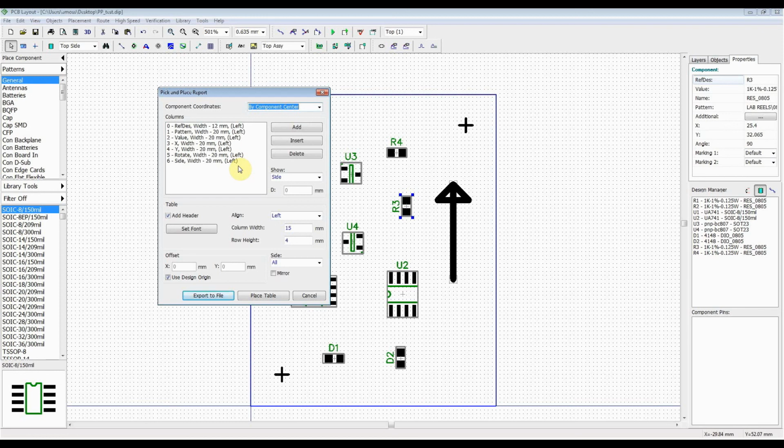Surface mount picking and placing, if you do it top and bottom side, you're in for a world of pain. Quite frankly, you can be placing components on the top of your board, and when you flip it over to place components on the bottom side, if you haven't reflowed it, you can start firing components off the top side because you're hitting them, making them bounce. Heavyweight components will drop off when it goes through reflowing. Components on the underside will probably tombstone. The surface tension is all out of whack, and gravity pulls the components in the wrong direction, or pulls them to tombstone, and they just drop off the board altogether.